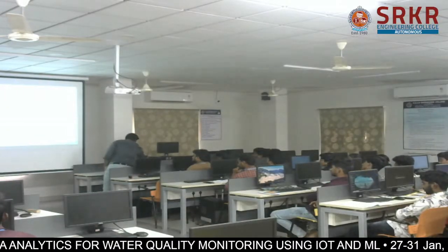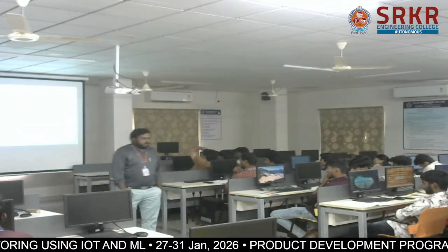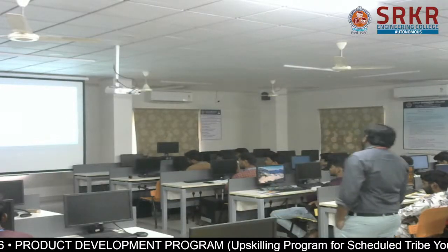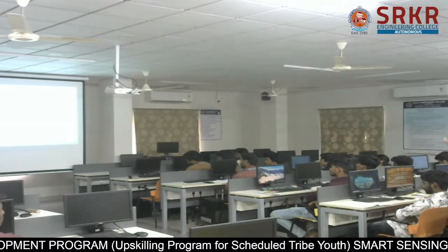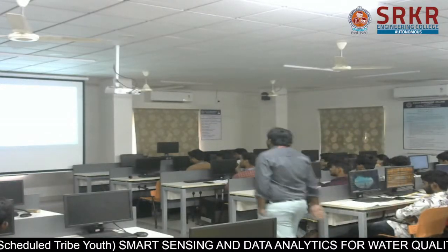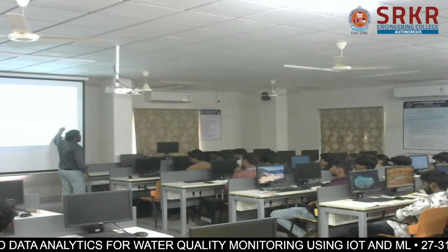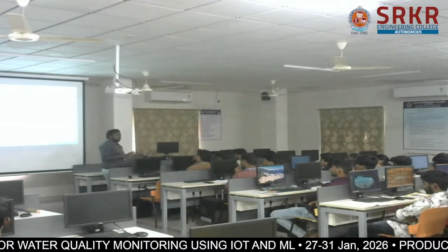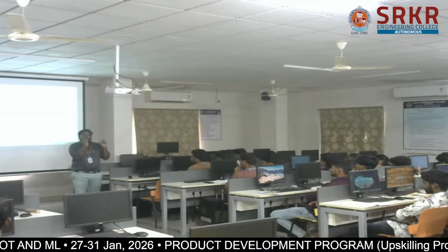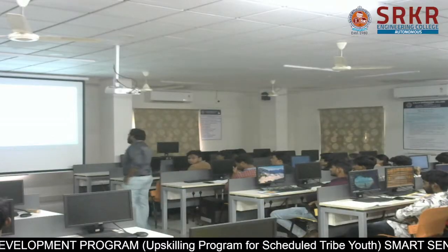And then analysis. If you see the analysis, in normal vibrations, the vibration should be 2 mm per second. Whenever faults occur in the system, that vibration will be more, greater than 3 mm per second. So based on that cumulative information, we can tell. You have to see the gradual increase in the value as well as the individual observations. You have to see whether this is temporary, transient or permanent. You have to take all these things into consideration before taking the decision.